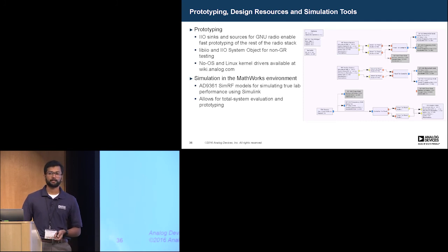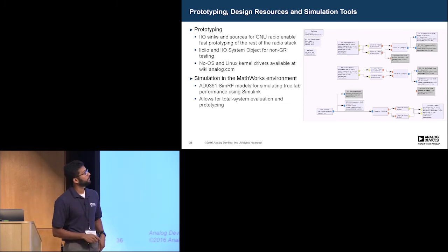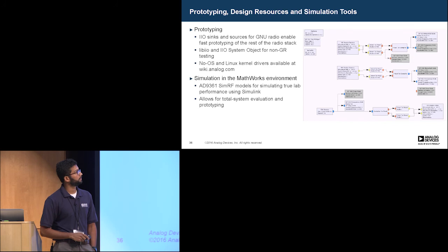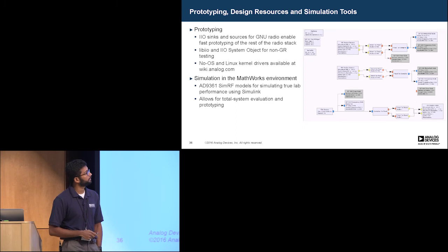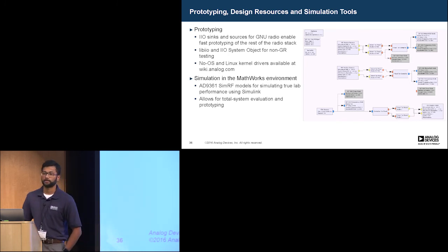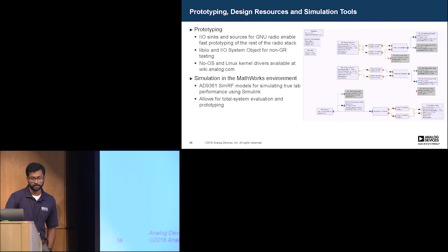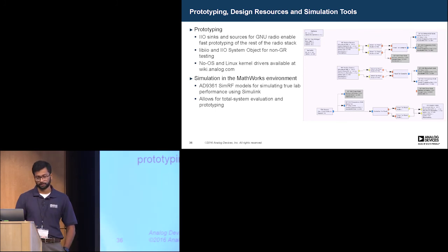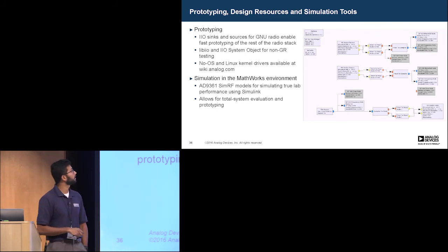So how do you get your hands on these toys now? Of course, you can use your GNU Radio blocks, IIO device sources and sinks. The 9371 sources and sinks are in the works, so you should be able to get a little bit more access into that soon, as you did with the 9361. So you could go ahead and prototype your modem stack on GNU Radio. You can also do your full system development with the API and the kernel drivers if you wanted to. The links to all of these references are in my notes on the PDF, so if you want to look through them, you can definitely find them.